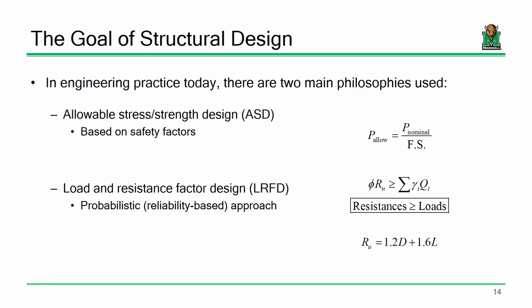Now, there are at least two general ways of doing that. One of them, which is probably what you're more familiar with, is to just use a factor of safety of 2. Take the capacity and divide it by 2, and that's what's usable. That's fine. In some areas like geotechnical engineering, there's really no other way of doing it. Any geotechnical engineer will tell you, you can do a boring right here and another right over there and get two completely different sets of soil properties. So you use the average properties you come up with and then incorporate a factor of safety that you think makes sense. Geotech is highly variable.